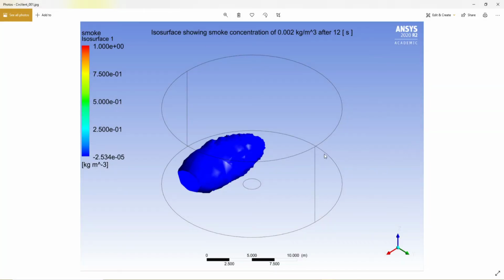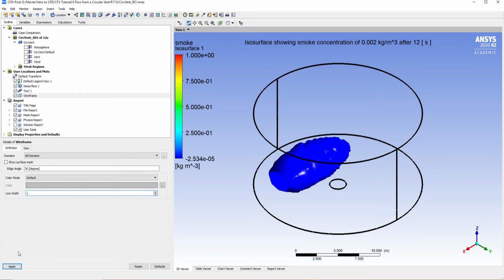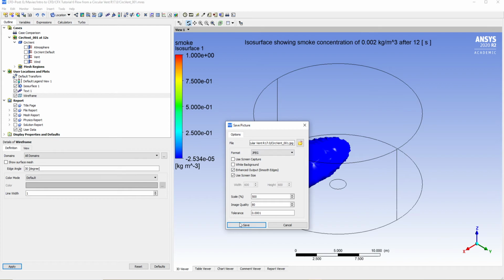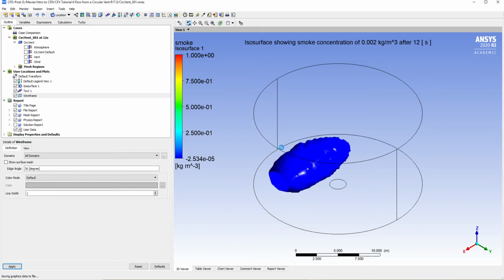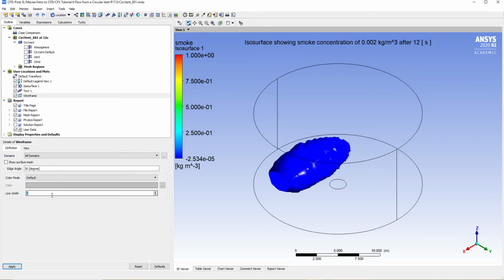See? I want to show you guys, if we didn't change the wireframe, how this would look, okay? So pay attention that we can see the lines of our domain very clearly, right? If we go back to our software and go back to the line width of 1 and save it with the same simulation, with same characteristics, you're gonna see a very clear difference, okay? See how much dimmer they are and how harder it is to see? So this is why we changed the wireframe to 5, so that our generated images are better, okay? So let's go back to 5. There you go.